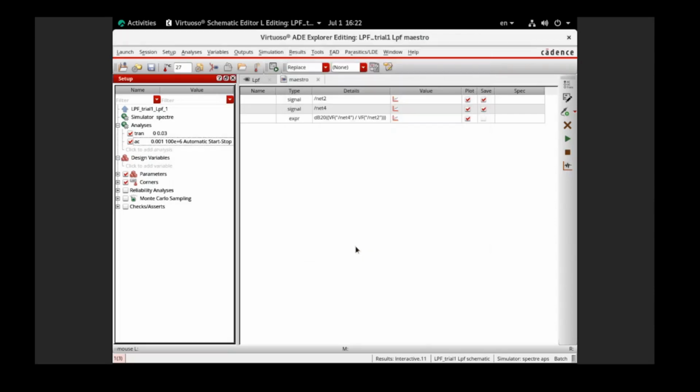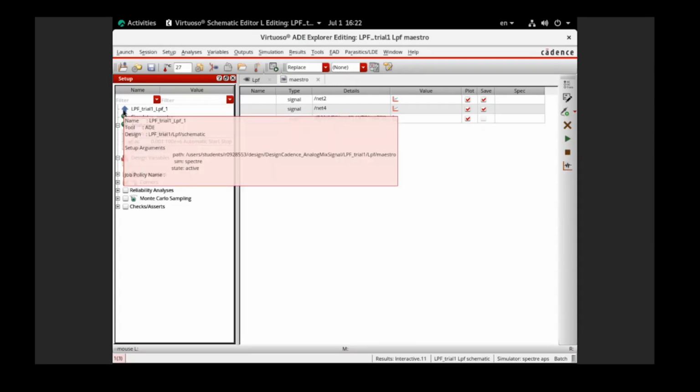So we click OK. Now we have the transient analysis together with the AC analysis. We can check both of the analyses at the same time. So when we run the simulation, we run both simulations. If you uncheck the AC analysis, then when we run the simulation, only the transient runs. So you cannot see the Bode plot anymore, but if you check both of them, you can see the results related to both simulations. I prefer having both in this case. And then we go back.